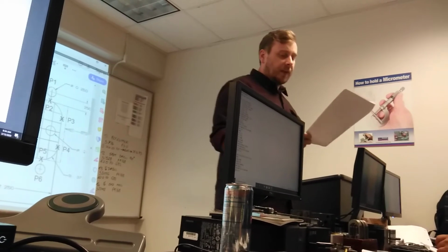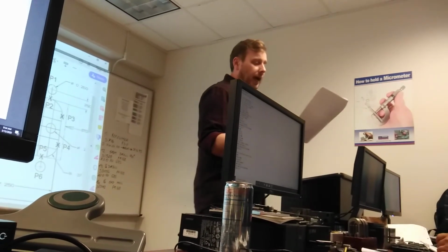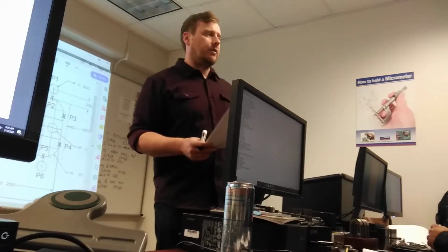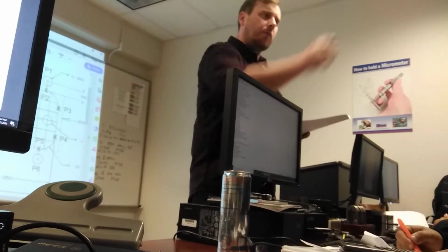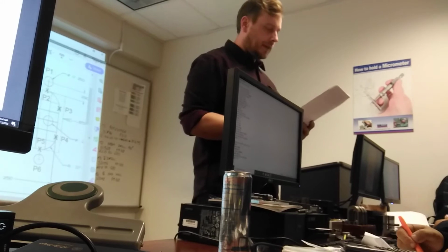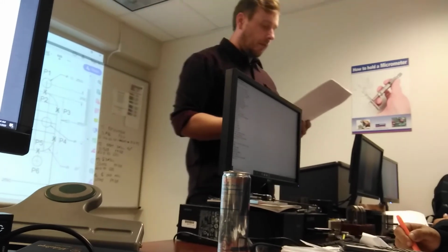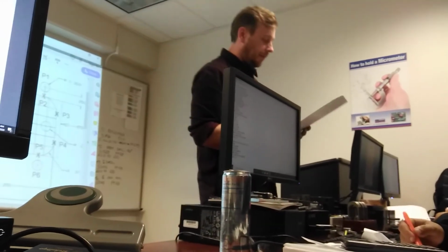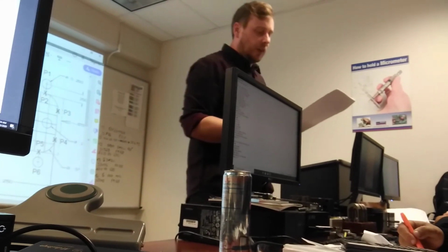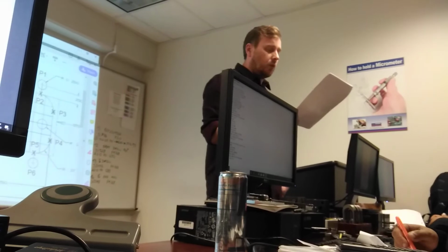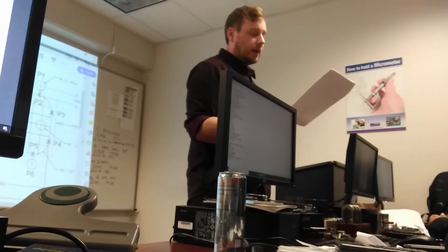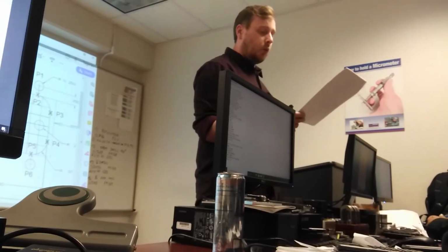So when you activate cutter comp, highlight the first sentence: select a clearance point. You need the tool to be away from the workpiece. So select a clearance point without cutter compensation, to a start point in the X and Y at least half the cutter diameter away from the part.